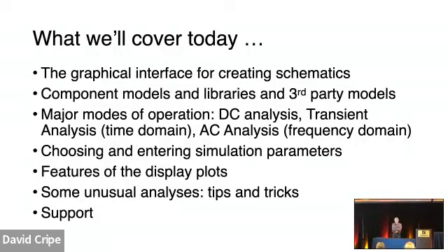I mainly want to talk about DC analysis, transient analysis, and AC analysis. Transient analysis being time domain, AC analysis being frequency domain. And talk about choosing and entering the simulation parameters, features of the display plots, which is really where your output is when you run your simulation, and then maybe some unusual analysis types and some tips and tricks.